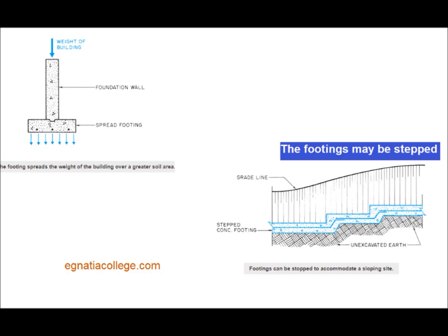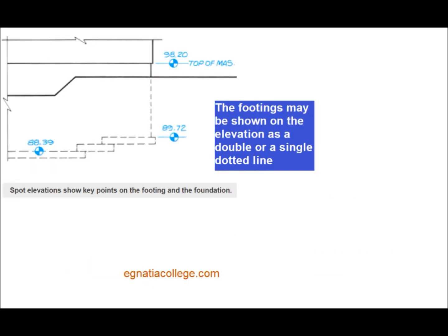The layout of the foundation walls and their footings is shown on the foundation plan. If the footing size is not indicated on the foundation plan, a consulting engineer will have to determine the size in accordance with the local building code and the conditions at the site. The depth of the foundation, including its footing, is shown on the elevations. To simplify calculating excavation depths, many architects indicate the elevations as key points along the footings.